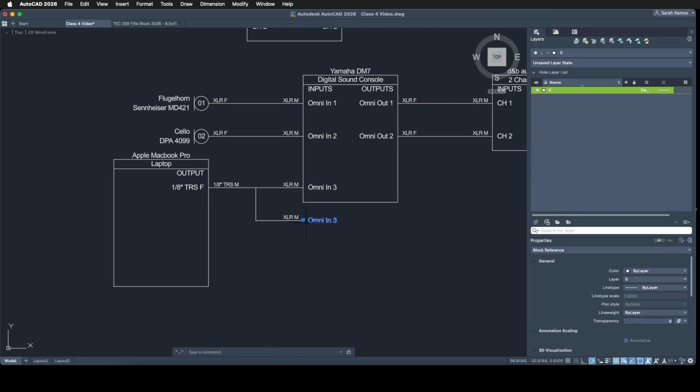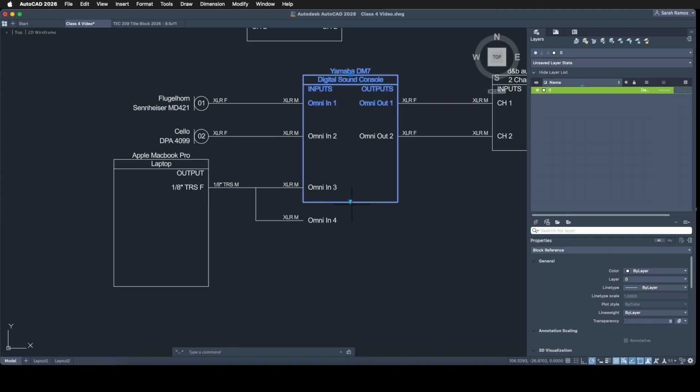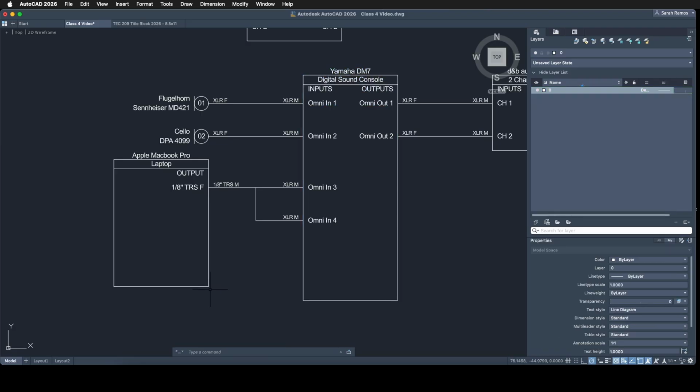So how do we space these vertically so it feels clean and even? There is another one of those. Depends on what you're doing. Whenever I manage to develop a convention, I end up having to break it because my system gets too complicated. I have some blocks in my personal workflow that I call spacers. When I want things to space out a certain way, like the distance between these microphones, for example, I will create a rectangle and fill it in with an obnoxious color and make that a block. Let's make one of those.